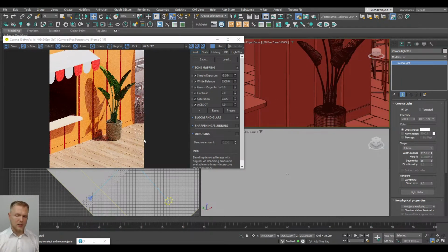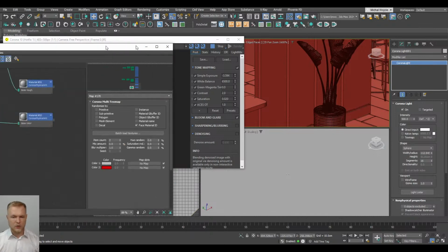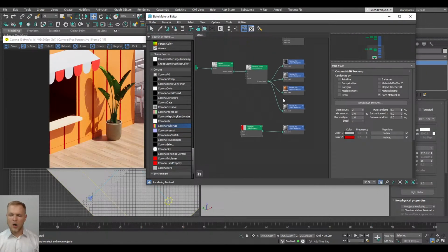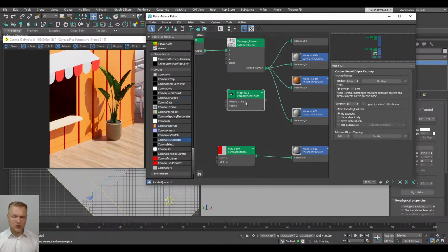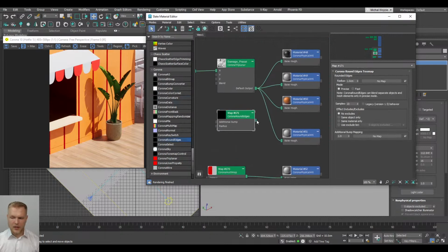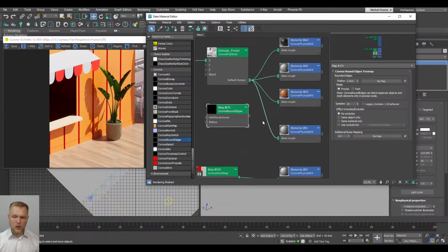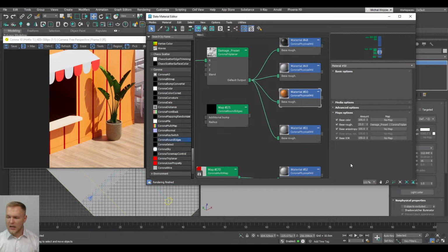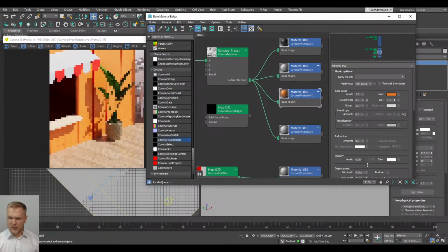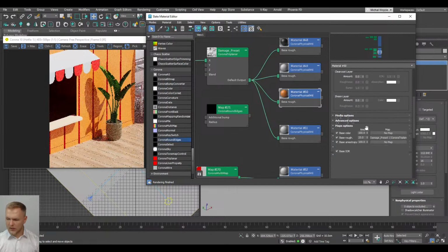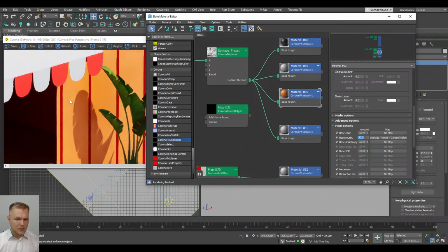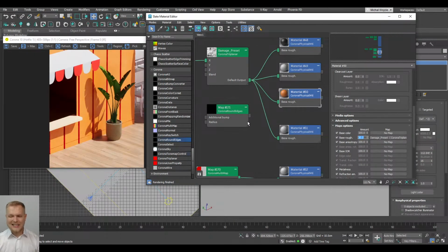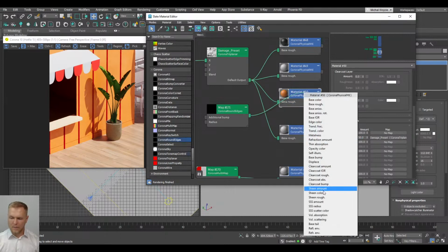Okay, so another trick that I want you to consider, or this is not a trick, this is just a solution. Another option that you can go for is Corona Round Edges, especially for materials, for metals and some kind of detail that you want to add in here. So let's go ahead and first of all lower the base roughness for the orange, because I want to see more of that damaged type of material. Let's go for 50. Okay, now we can see that there's a little bit of that extra shine going on. It's not enough yet, but let's go ahead and now add the bump.